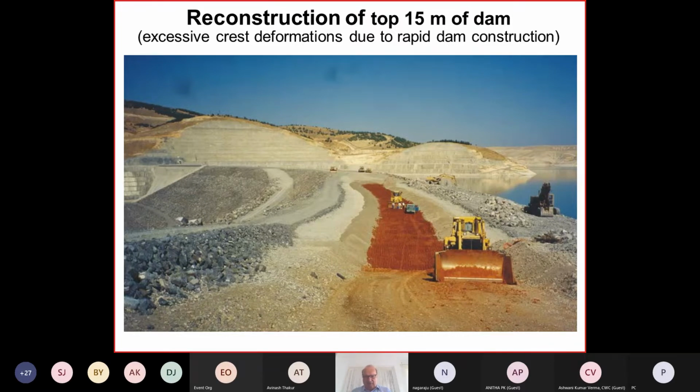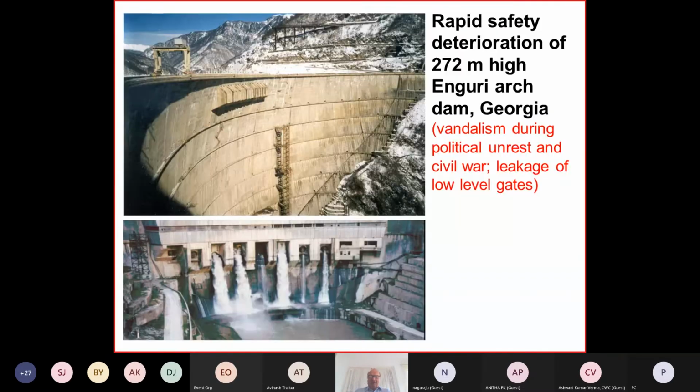But if it is built into rockfill dams, because of the interlock, the size of the porosity and the void ratio, the modulus of elasticity of the rockfill is actually low. In some cases, it's only 30 megapascal. In Brazil, we have quite a few of them. So you have to be careful if you feel that a high-strength rockfill will give you a rockfill dam with a high modulus of elasticity. It's not enough. Not true.